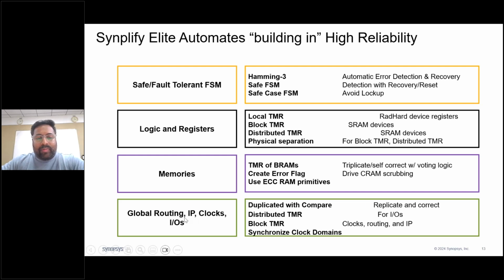To protect your global routing, IO and clocks, we support DWC, which is nothing but duplicated with compare. Instead of replicating, we duplicate the logic and then compare it. So if any discrepancy is there, it will raise the flag. Okay, so this is a very important feature available in Synplify, which is mostly used by your aerospace and defense customers.